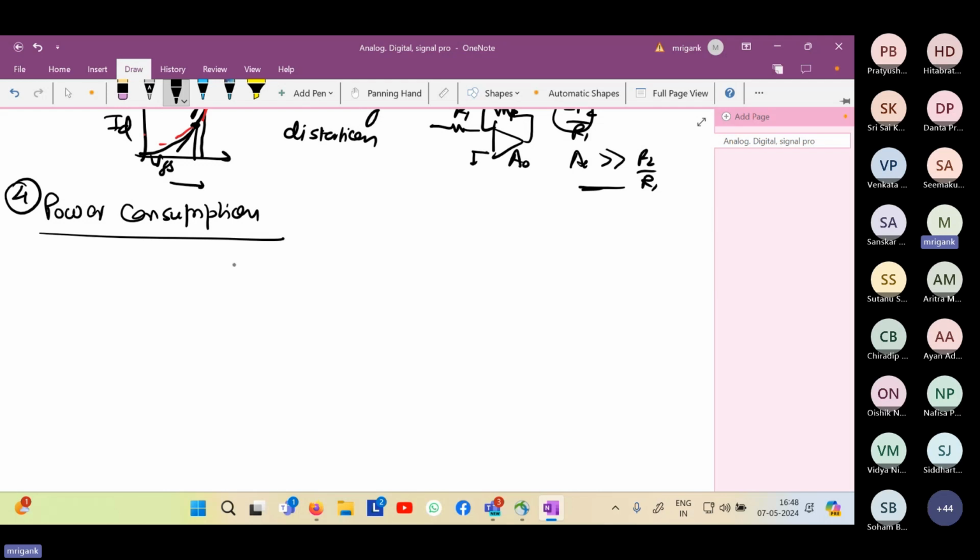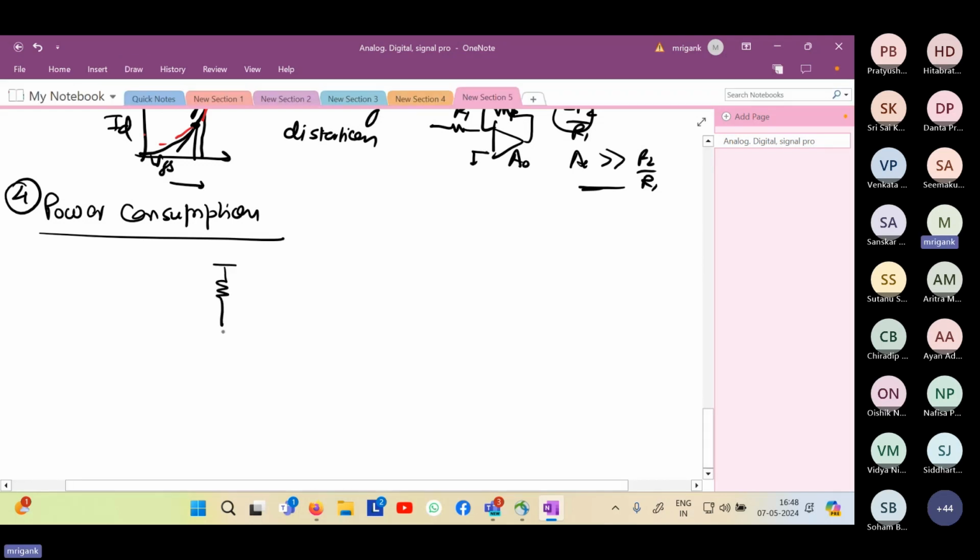Analog inverter. A simple single stage common source amplifier is the inverter, right? So you can operate this as an inverter. Apply VDD. Output will be VDD minus I times R. If R is sufficiently large, it will go to 0.